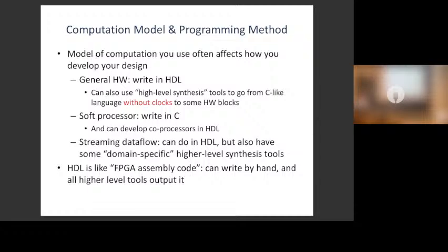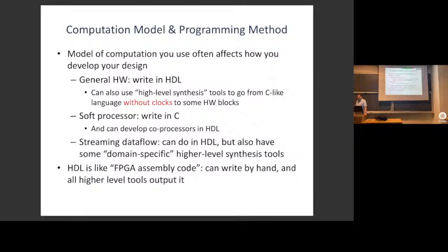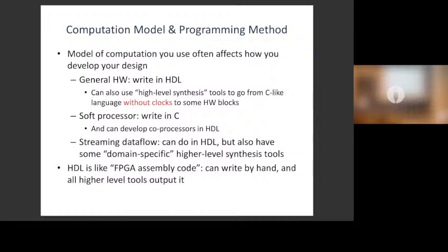Yeah, so the idea is that it is a little higher level. I mean, all of this stuff is in a sense programming, but a high-level synthesis language has some more constructs; it looks more like C with some annotations. There's no standard, okay? So for high-level synthesis, there are a lot of different tools. The most common type uses a C-like syntax or C syntax exactly, which usually is not enough information to generate efficient hardware, so then they add in some pragmas, some extra guidance to the tool to tell it how to generate hardware.